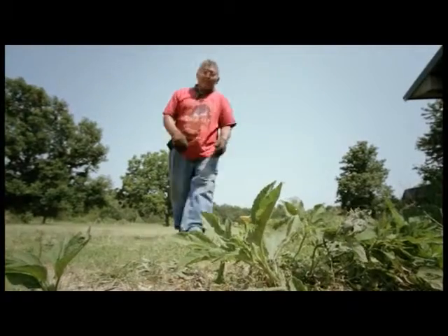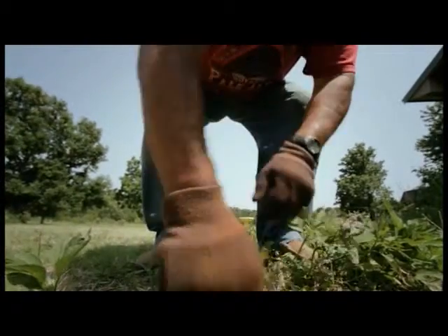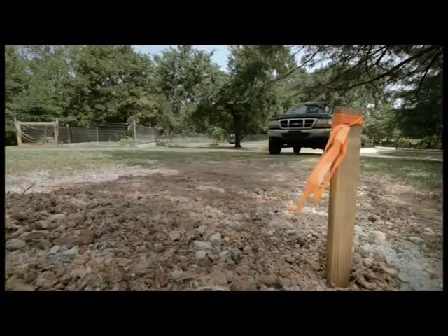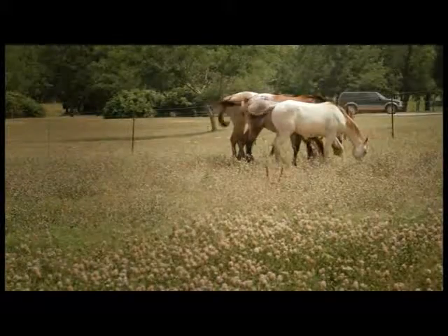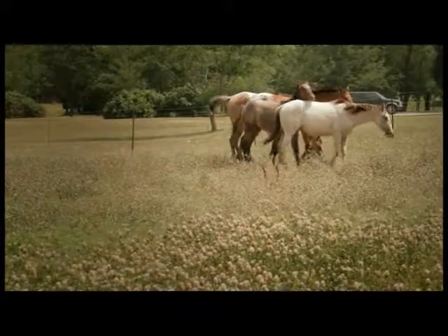You are responsible for keeping the septic tank and sewer line accessible. Keep the area free and clear of trees, shrubs, decks, patios, and playground equipment. To avoid damage, do not drive vehicles or heavy equipment over the septic tank or sewer line. Keep livestock off the area.